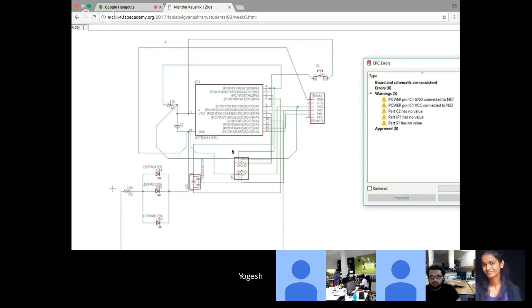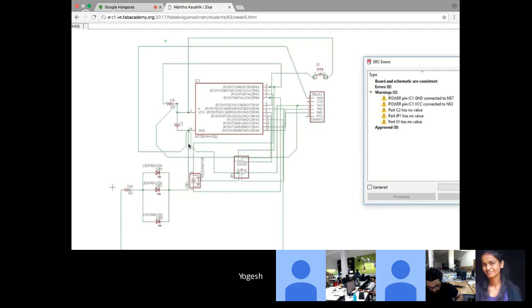So what you can do is, rather than connecting all these wires to this point, you can name this node. Consider that it is node 1. Whatever you want to connect, you can right click on the wire and name it node 1, connected to node 1. This is very useful when there is a very complicated circuit. I was looking for that feature actually, so thank you. Yeah, that's the same feature as present in Proteus as well.